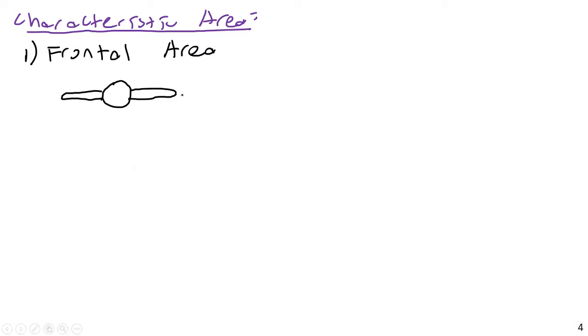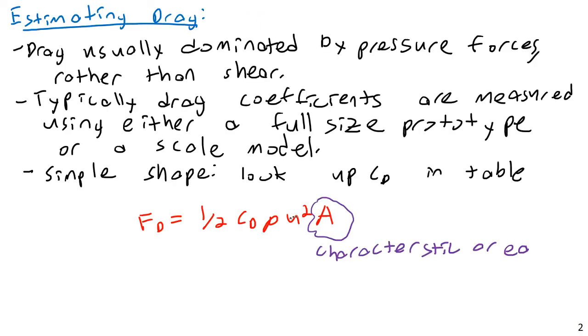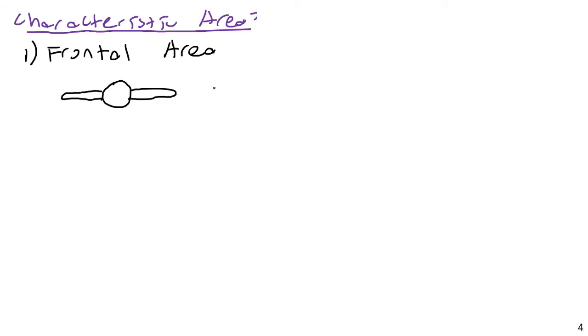And so planes obviously need to be as light as possible. When you have to lift your own weight instead of, say, just carrying it on the ground, weight becomes absolutely critical. So you need to minimize weight, and your drag also becomes critical. So you absolutely need to minimize your drag force. And in this system, the drag force is dominated by the frontal area. In this case, again, the example would be a plane.